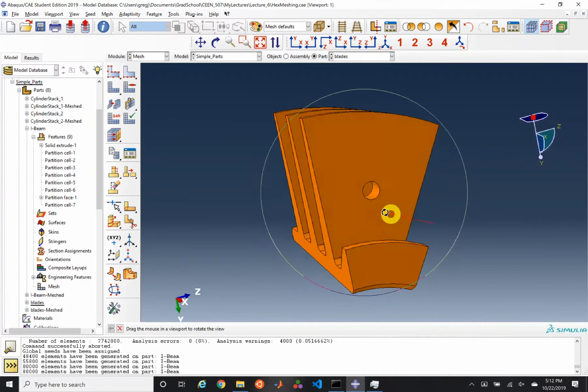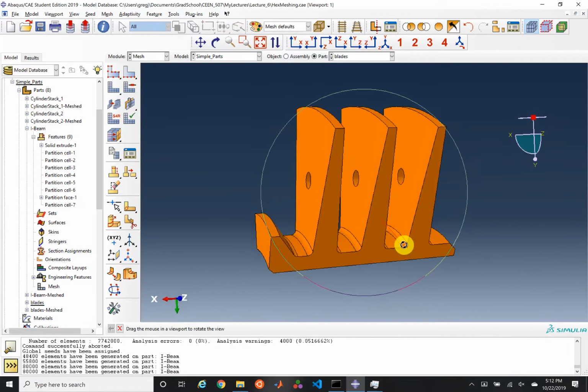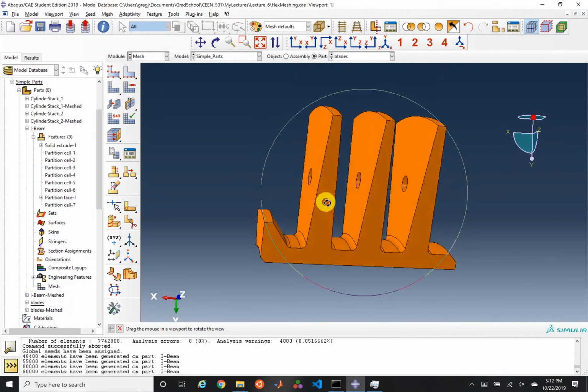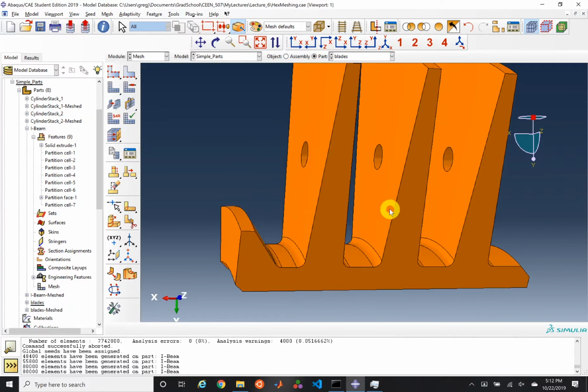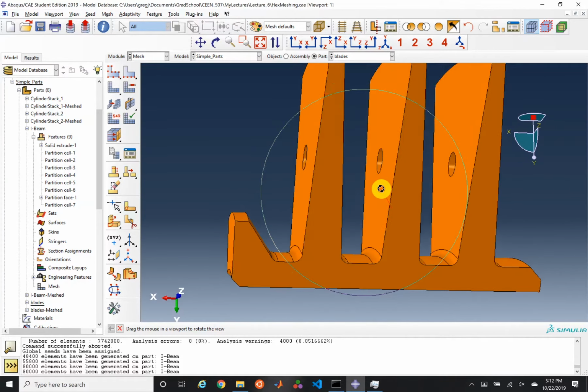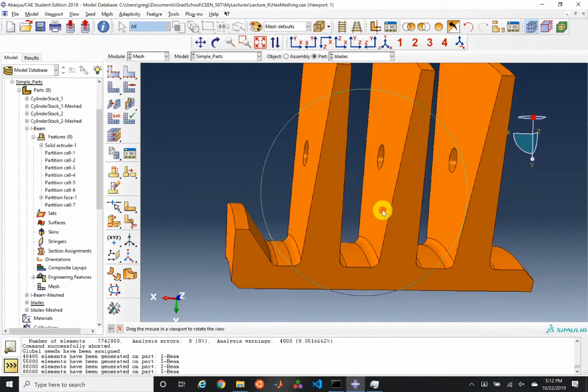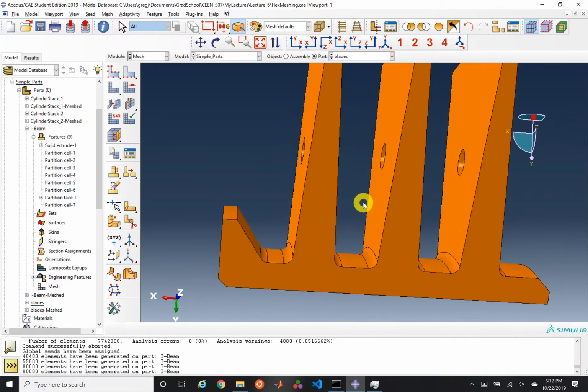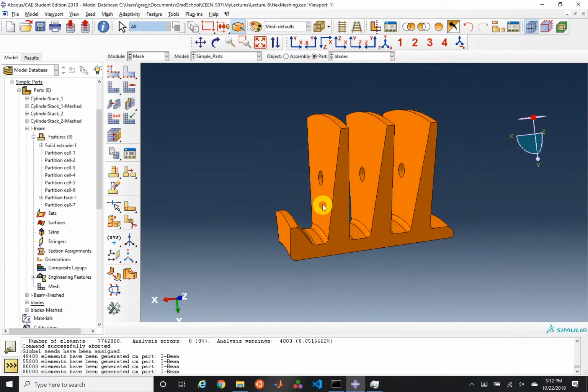Lastly, there's a problem with these blades, and I just want to walk through it. This is maybe a bit of a challenging problem to think about, how to construct a mesh. But one of the things I typically recommend is that you first make some very simple cuts of your problem that make it kind of blocky. So maybe pause the video and think for a little bit about where you would first separate out the problem.